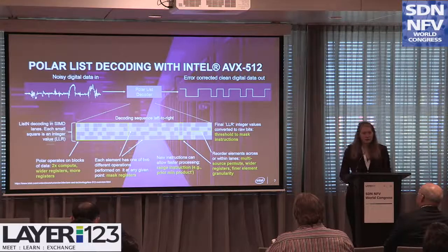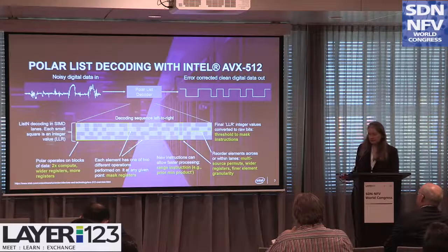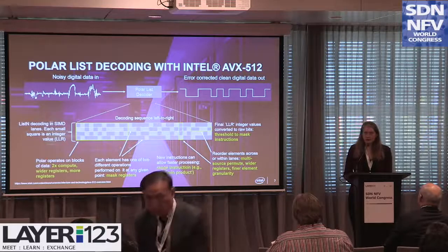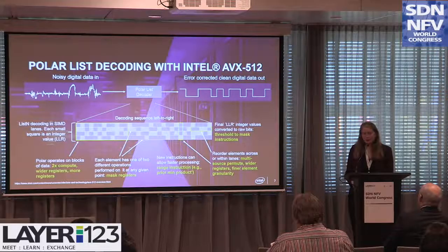Then it also introduces the concept of mask registers, and that allows us to perform operations on just a selected group of that data. So I've got grey blocks and blue blocks up here. Say the grey blocks might represent bit 0 and the blue blocks bit 1. Quite a lot of operations we would want to do something different based on whether we have a 0 or 1. So maybe for the grey blocks we want to do additions, and for the blue blocks we want to do something else. If we use these mask registers, we can make that selection combined with the instruction, whereas previously we had to do some extra logic to be able to do that masking.